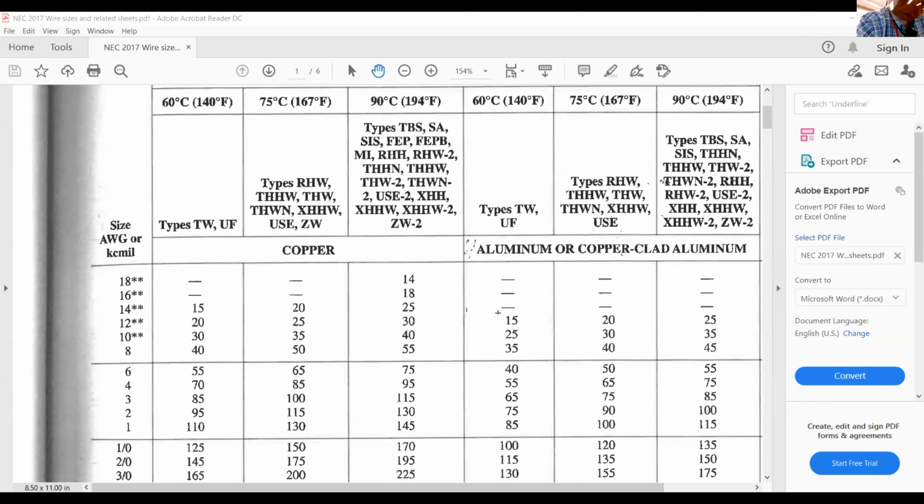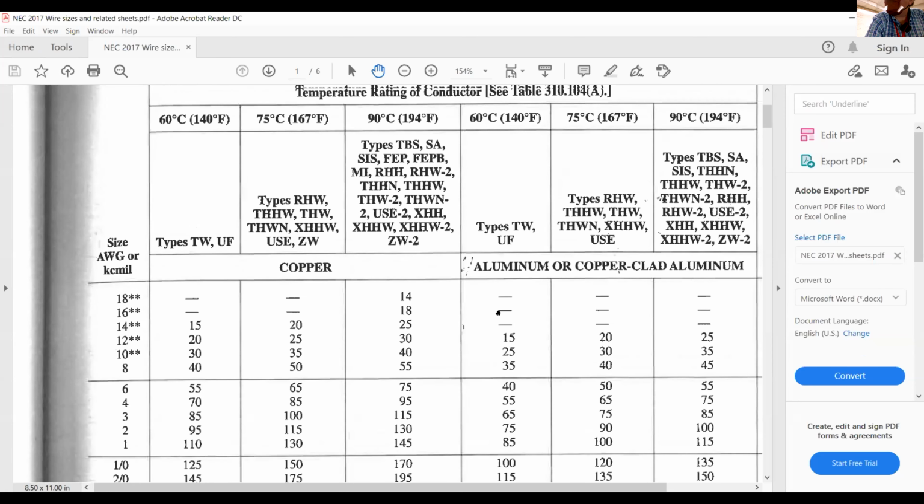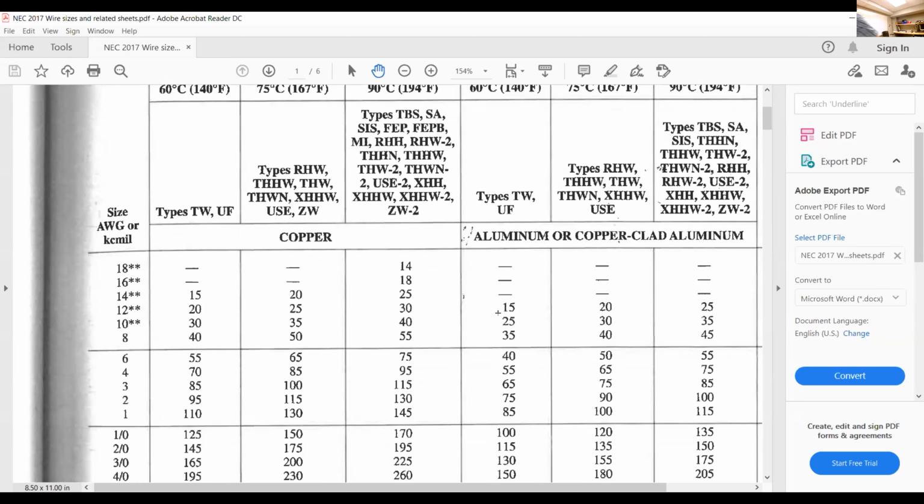Here's another one that a lot of folks never look at. Now let's say, for instance, Jamie, that you were using, maybe you were in the center column here, or maybe you were even over here, maybe you were allowed to use that column there, and you're using a number 8 wire for the pressure washer, okay? Number 8, you can pull 55 amps off of that wire. Now, it's conventional, and it's conditional on this.